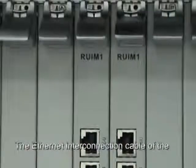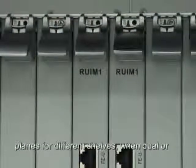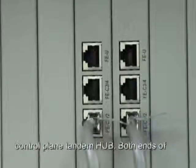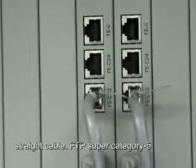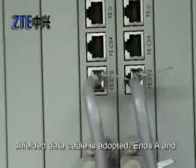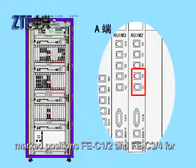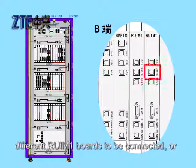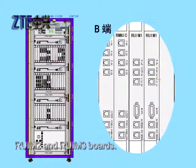The Ethernet interconnection cable of the UIM control plane interconnects UIM control planes for different shelves, when dual or multiple shelves form an office without a control plane tandem hub. Both ends of the cable are crimped plugs for 8P8C straight cables. An FTP Super Category 5 shielded data cable is adopted. Ends A and B of the cable are connected in turn with the marked positions FE-C1/2 and FE-C3/4 for the connection of different RUIM boards, or the marked positions FE1 to 10 of the RUIM2 and RUIM3 boards.